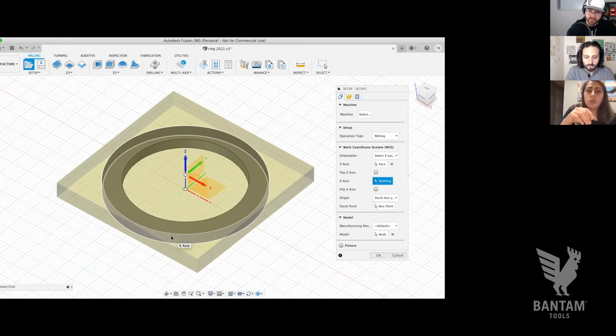And so when you're in Fusion, you have to specify that corner. Like Pete said, you're putting a stake in the ground. It's almost like back when we were doing the offset tool back in CAD, everything is going to be a chain from that one point that you choose. Got it. That might be a little bit more general, but that's how I like to think of it: you're orienting your model within the stock, and then you're orienting the stock within the machine.